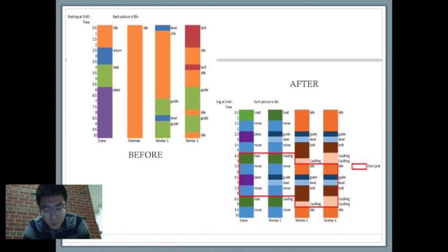We will assign the foreman to work on the placing stage because if he works on preparing the panels, then the crane will block him from overseeing the construction site. As a result, we can reduce the total amount of people on site to 4: 1 crane operator, the foreman, and 2 workers. This will get the scheduled activities done at the same time while being more effective since the crew has less idle time as a whole.